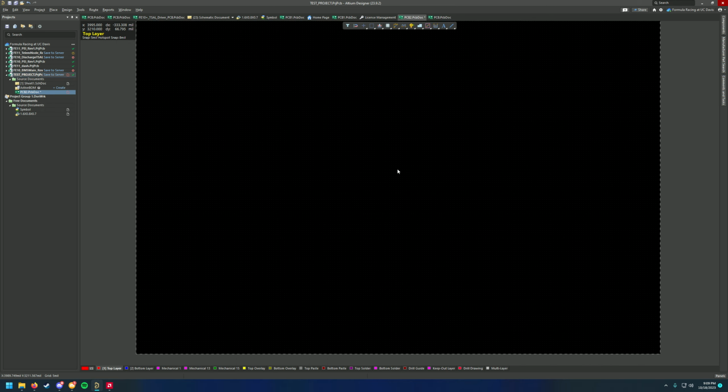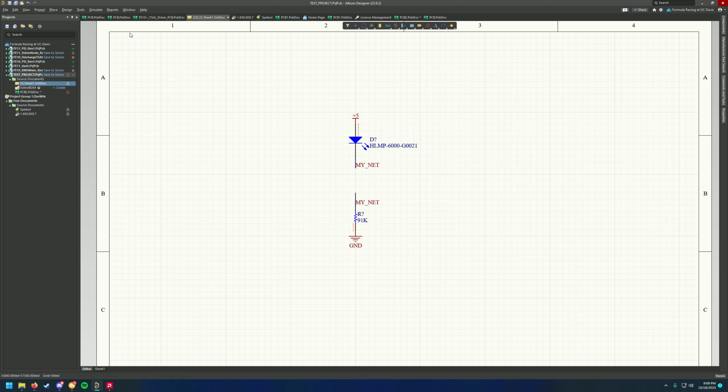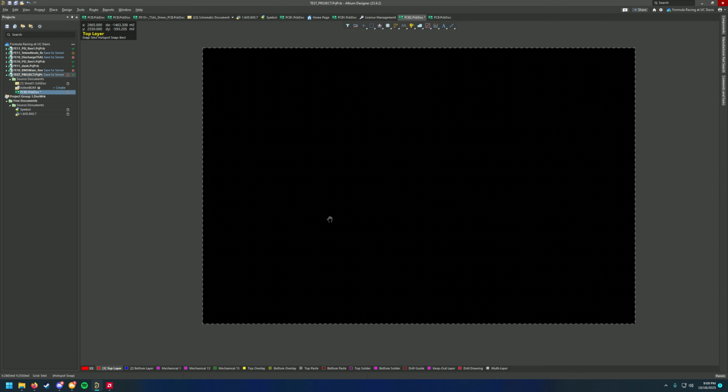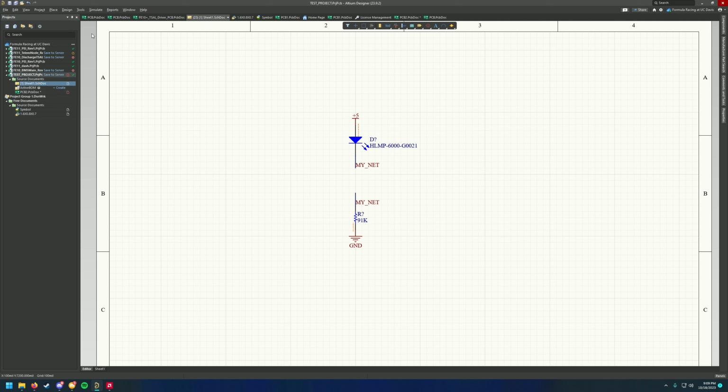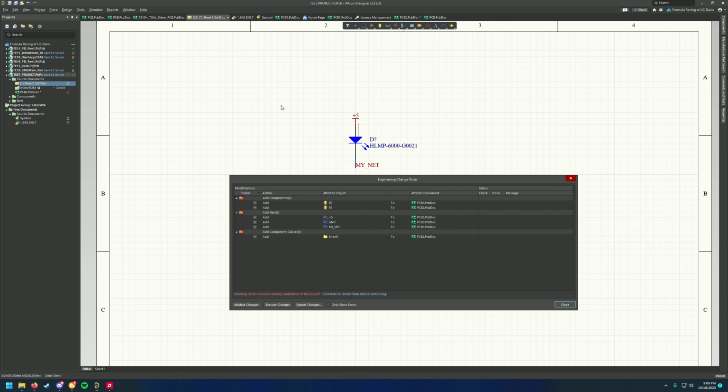The only way you ever want to add things to the PCB document is to go back to your schematic, go up to the options up here, and hit Design, Update PCB Document. What that's going to do is take all of the stuff you made in the schematic and move it over into the PCB. You can also use the shortcut. You can see the D is underlined, so I hit Design, and then the U is underlined for Update, so I can hit U. So DU will do the same thing.